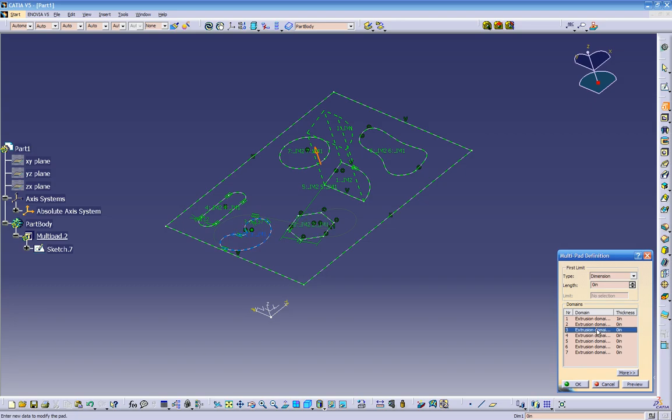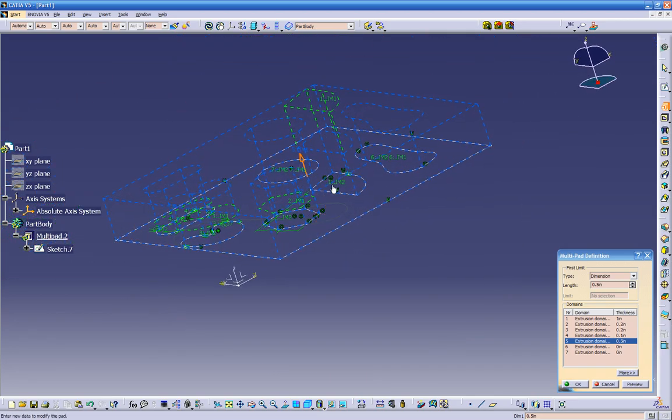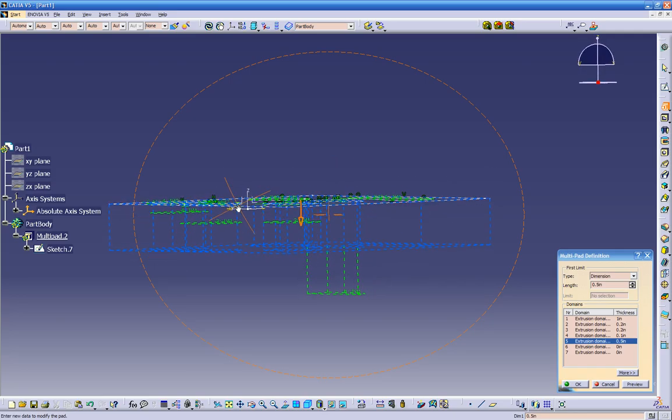Let's go to this guy. With this one, we can hold the control key down, and we can give a dimension to both of them at the same time. Okay, let's dimension this guy right here. Let's make it 100,000. This guy right here, let's give it 1/2 inch. Actually, let's go reverse. So click on the arrow and automatically it's going to snap on the other side.